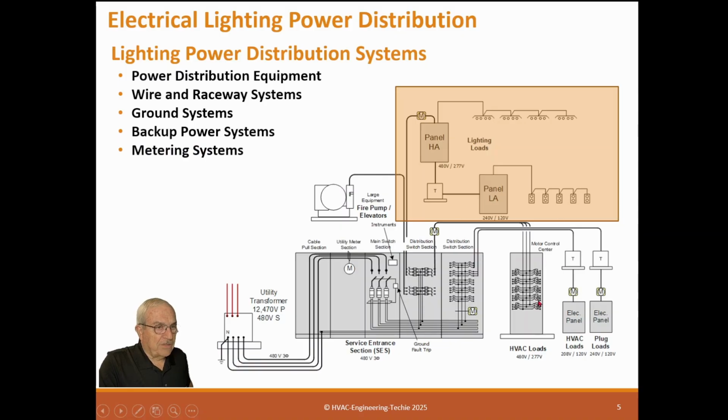If we don't have sub-metering and we just rely on the utility meter, then he sees the whole bundle at once, and the HVAC appears to be really diluted. So any change he makes will be a very small change in the total energy. That's why we like to have sub-metering.